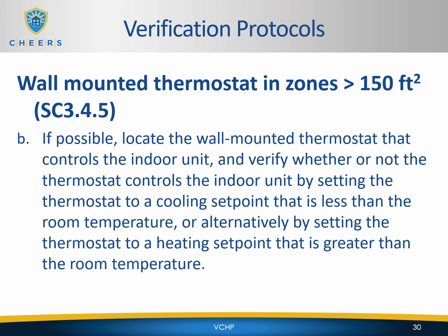If possible, locate the wall-mounted thermostat that controls the indoor unit and verify whether or not the thermostat controls the indoor unit by setting the thermostat to a cooling set point that is less than the room temperature, or alternatively by setting the thermostat to a heating set point that is greater than the room temperature.